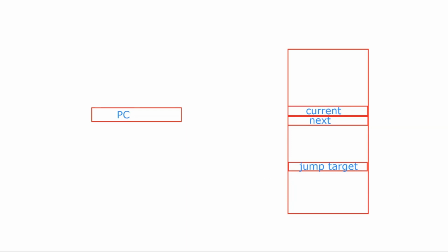What you see here as instructions are 32-bit words. Each instruction is worth 4 bytes, and a full 32-bit memory address addresses each individual byte. So the addresses of these instructions are always multiples of 4.